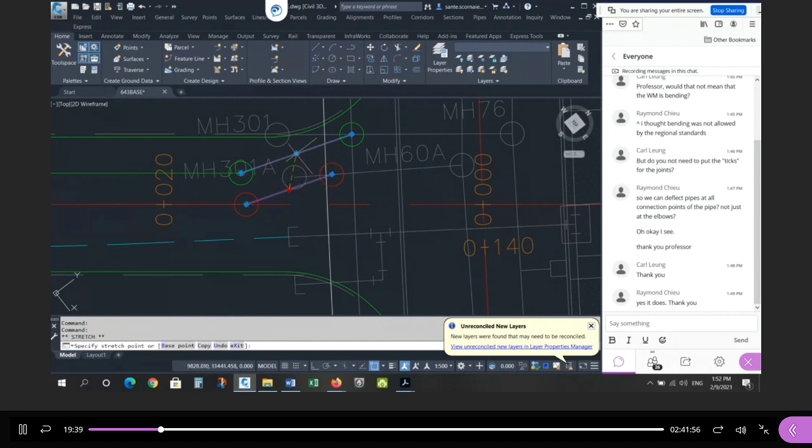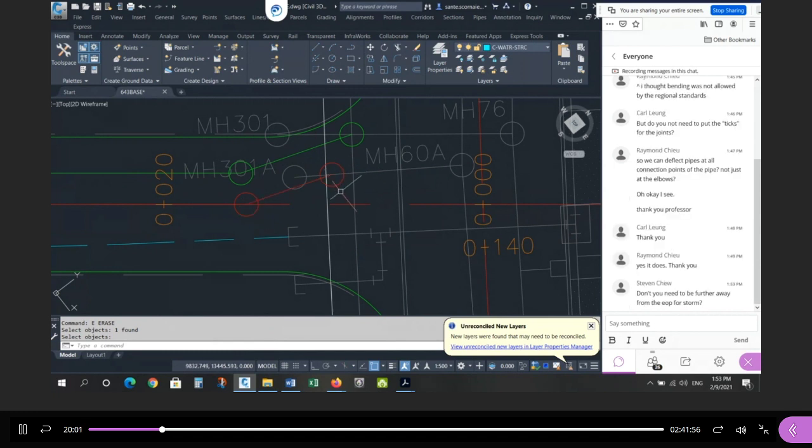If I take one and put it on top of the other, they're actually parallel. Some order of standard, right? So you'd like the pipes to be parallel. I drew this one first from this position to somewhere on this pipe. Then I made a copy of this and offset it by 2 meters. Standard position, a typical 2-meter layout. Then I found this intersection and this intersection, and you can see they're both outside the zone.